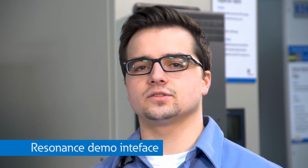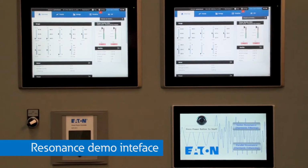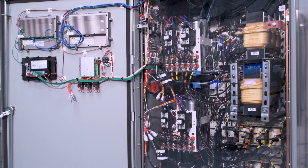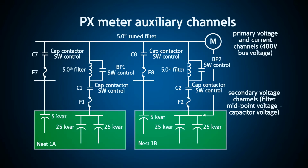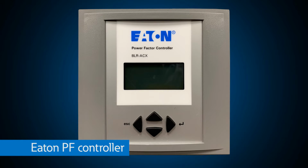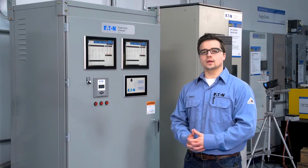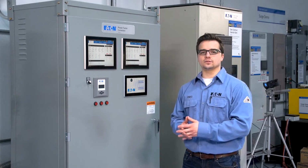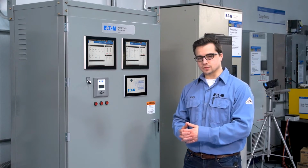We designed the interface to allow us to program various scenarios with an Eaton touchscreen PLC and SmartWire controls. Inside this demo, we also have two Eaton Power Expert meters with aux channels to monitor various points on the capacitors and filters, including the voltage between the capacitor and inductor on a filter, as the voltage rise on a capacitor is often a concern that we can demonstrate. We also use this Eaton Power Factor controller to mimic what would be done with an Autovar cap bank that automatically switches in and out steps or stages of capacitors or filters.